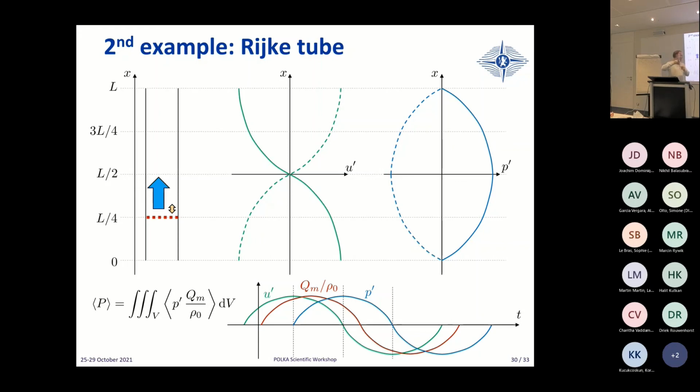To have this phasing of the monopole with the pressure, you count actually on the time lag. So this is the time now. This is the acoustic velocity field. This is the acoustic pressure field, at the location of the grid. And the thing that is working out is because you have actually a certain time lag between the modulation of the acoustic velocity and the heat transfer, because your thermal boundary layer needs a little time to adjust. If I enter into the details, the year will kill me. So bear with me, there is a time lag in the system.